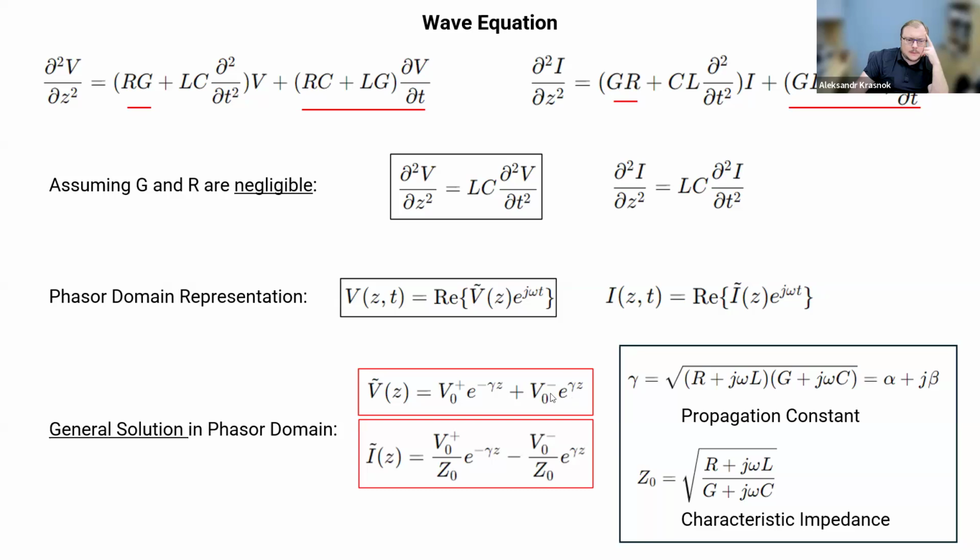And this gamma is the propagation constant, which has both a real part and an imaginary part. If you forget the real part for a moment, the propagation constant will be purely imaginary. And if you plug in this imaginary gamma here, it will be simply a harmonic function of z. Z is a coordinate, so it will be a sinusoidal wave along these wires.